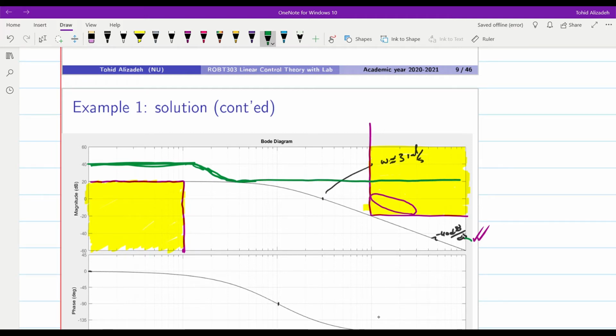In this case, the steady state error requirement will be satisfied. Crossover frequency will not move. It will remain as 3 radians per second. And the amplitude plot will not enter into the dangerous zone for the noise attenuation. And we will be happy with all the requirements, hopefully. And looking at this kind of controller, you should think about using the lag compensator.